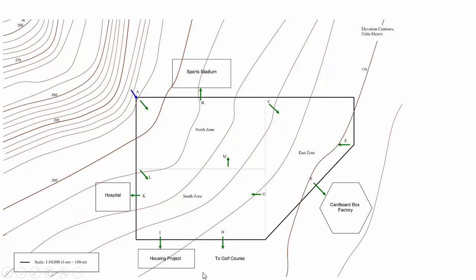This is the map that I edit a little bit from year to year, but it's the basis of your design project that I've already given you a sneak peek of. Here we have a contour map of different elevations, and so you can see in this map you've got the high part of town and the low part of town. This is relatively steep. You can tell that because the contours are close together, whereas this part of town is